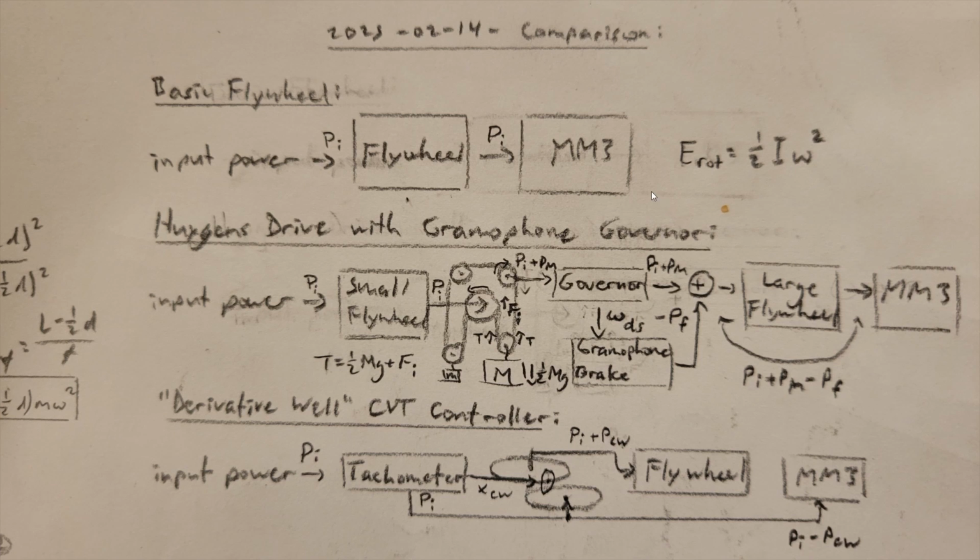When we add a flywheel, we give it a large moment of inertia and gear it up to rotate much faster, contributing a much larger rotational energy to the system. Thus, that same change in system energy will incur a smaller change in the system's speed, which makes it tighter.